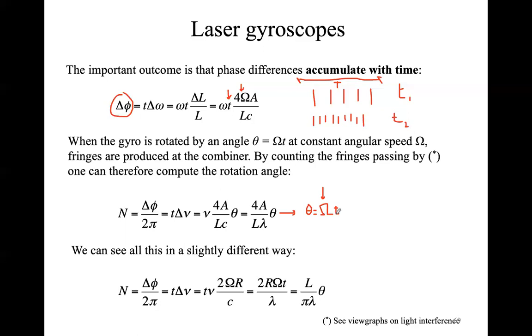So with this expression here, you are able to determine the number of fringes that you have from a variation of your spacecraft attitude by angle theta. If you have a variation of angle theta of a certain amount, 1 degree or 2 degrees, you know the amount of fringes that you can expect from your detector.